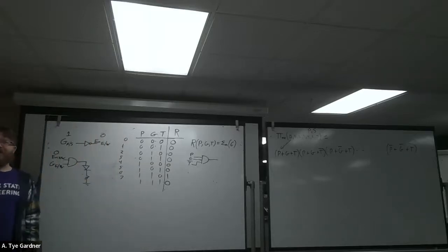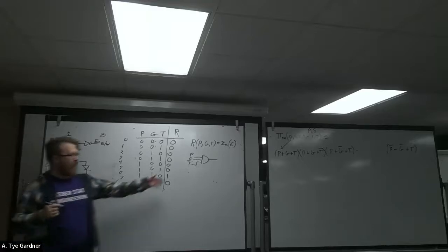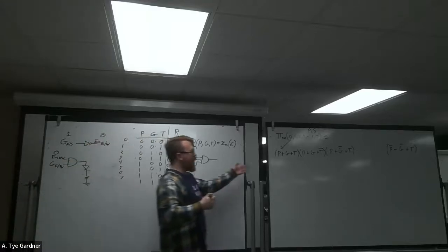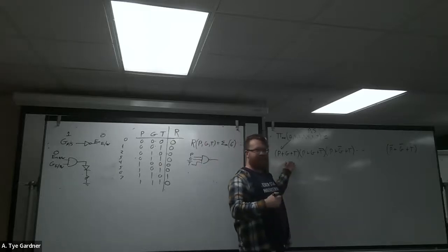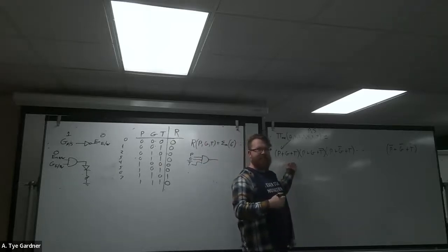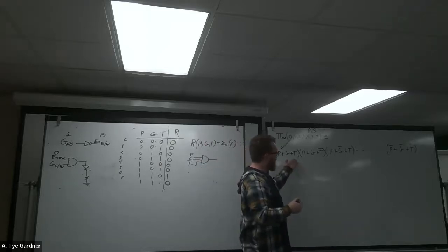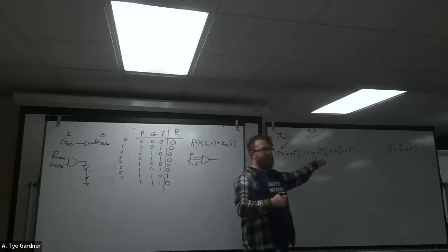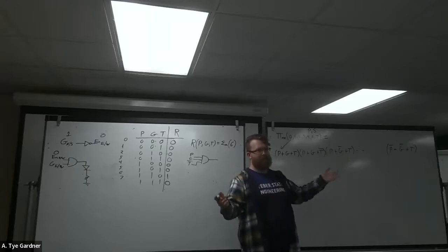And now you can see why you might choose the ones or you might choose the zeros, right? Because if I choose the ones, I get 1 AND gate and nothing else. If I were to choose the zeros, I get, well, a lot, right? I need an AND gate that has 6 inputs to it. Sorry, 7 inputs to it, and I need 7 3-input OR gates.